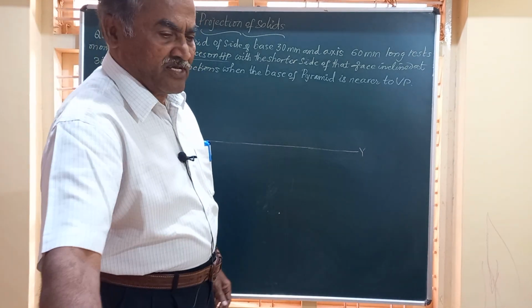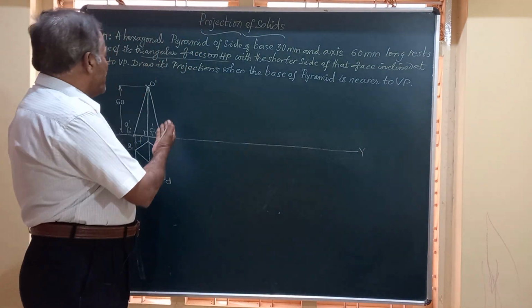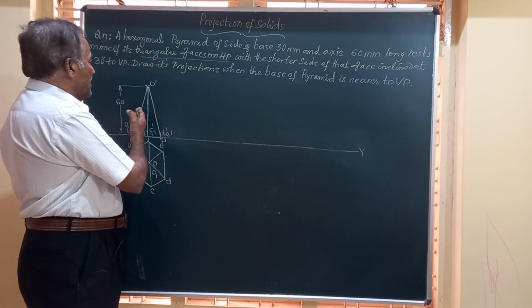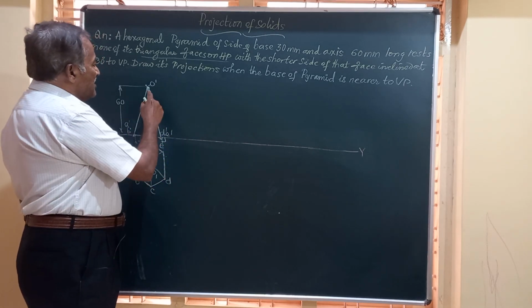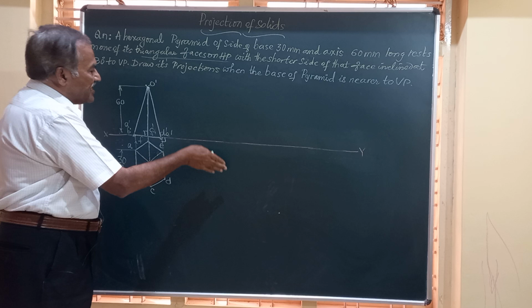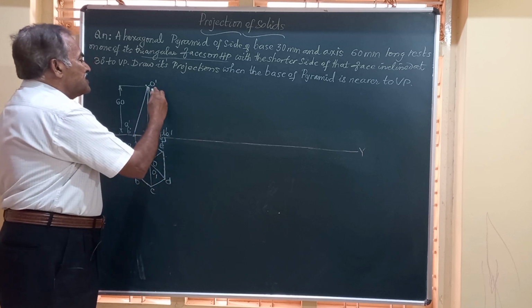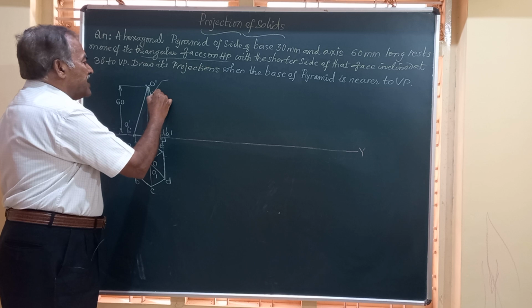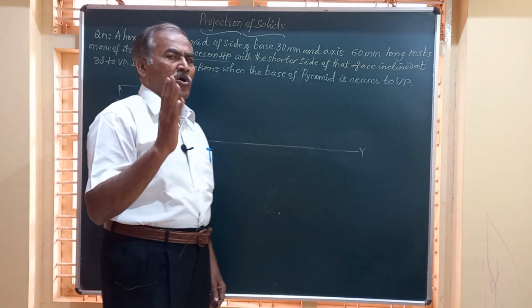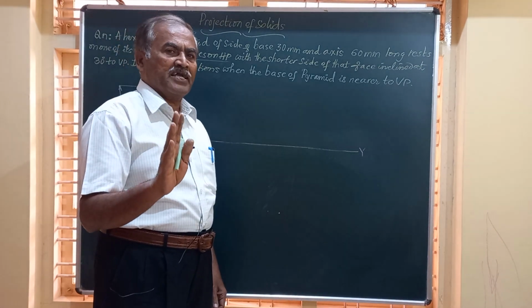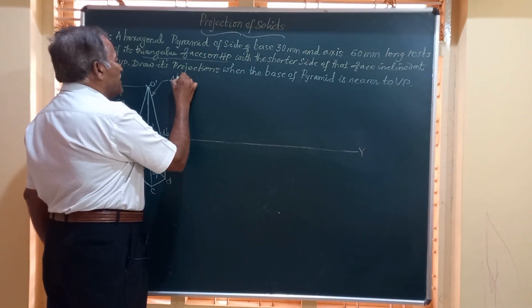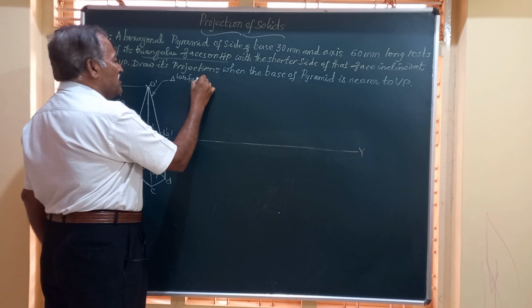Friends, what comes next? After this, if you observe the front view of the solid, the last line, either on the left or to the right, you find the line having 3 points. For example, since we are going to tilt the object to the right, let us consider this line. This line has 3 points, namely O, D and E. Whenever you have 3 points on a line, it represents a triangular surface. I'll write down here, it is one of the triangular faces of that pyramid.